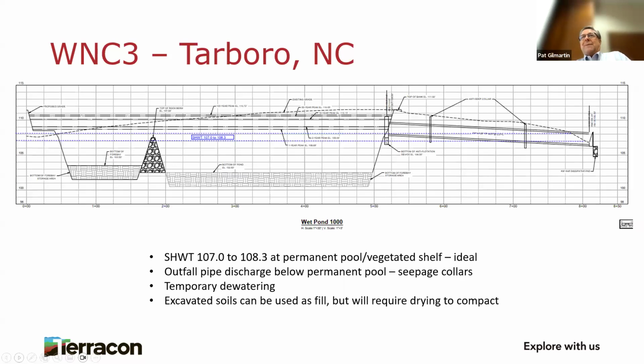The main thing about outfall pipes and seepage, and I don't think I mentioned it, is that it's really hard to compact backfill around pipes. So if you have a perfectly flat trench and you set a pipe on it, and you've got to compact backfill underneath that, with low permeability clay you can never get good enough compaction around it. So seepage collars or diaphragms, if you prefer, to collect rather than dam up the groundwater, is something that I would always recommend for an outfall pipe.